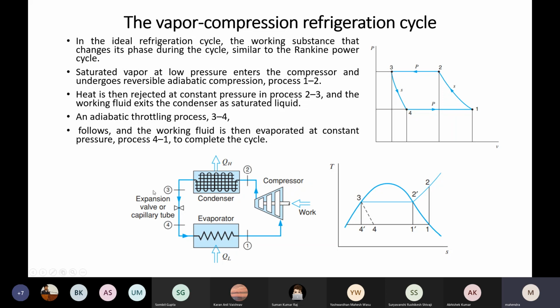So here, whatever expansion is there, in case of Rankine power cycle, wherever you are expanding, you get certain work. That is only shaft work you are getting. Then that work you will be connecting to the generator. That generator is producing electrical energy. The purpose of the generator is to convert mechanical energy, which is the shaft rotating at high RPM.